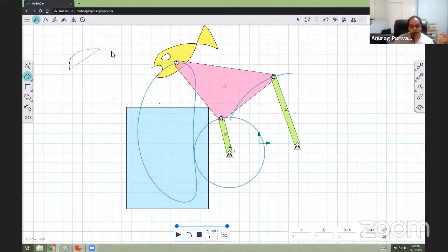So I can draw a closed curve, and I'm going to draw something that might look like a fish, and my drawing is not very good. Okay, well, it doesn't have a mouth. So what I'll do is I'll draw another shape over here. Okay, but that doesn't look like a mouth. So I can do what we call Boolean operations, where I can add and subtract and do these kinds of things. So I'll long press, do a subtract this from this, right? Now I got my mouth.